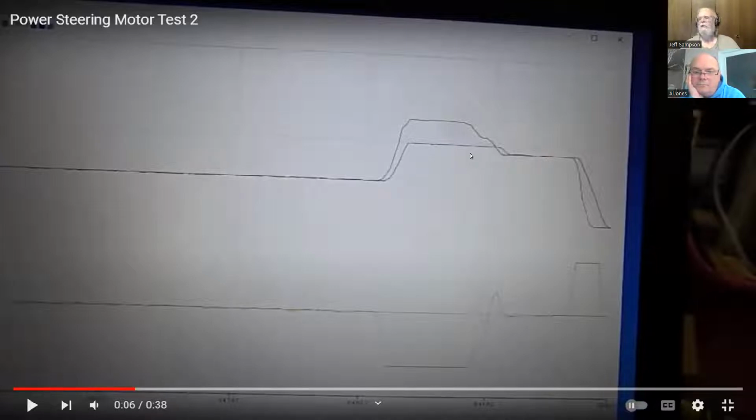You might think, well, I'll just set a limit on my steering and say if I'm within 500 counts of the hard stop, limit the incoming number so it can't go any farther than that. But it's still going to control. If you're in the center and you say go out to this point on the right, it's going to go over there, but it's going to overshoot and oscillate back and forth. If it goes right up against a hard stop and you're still driving with full power, you're going to smash something. This should prevent it from doing that.